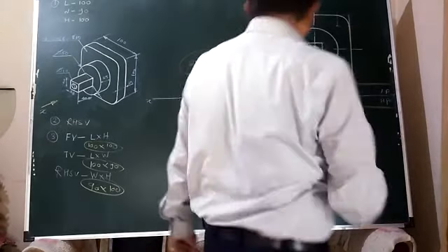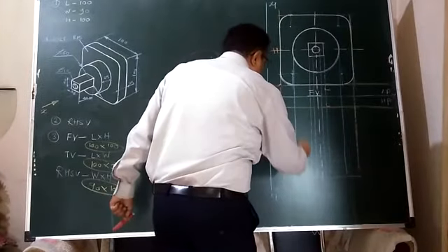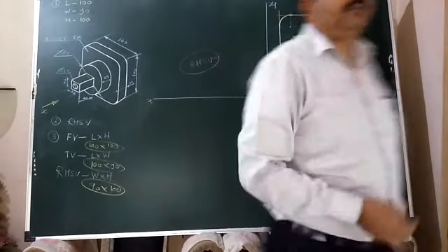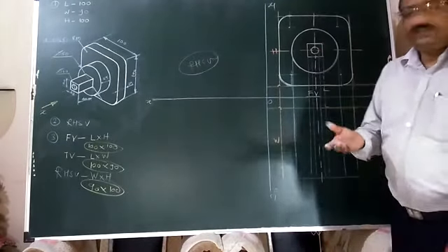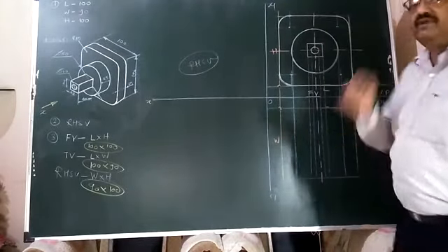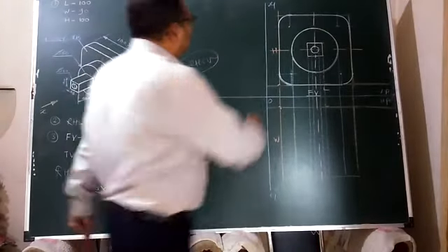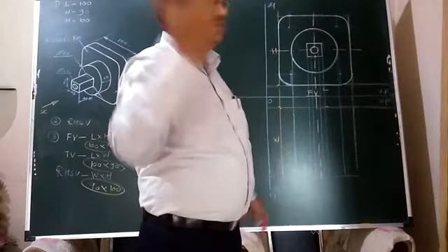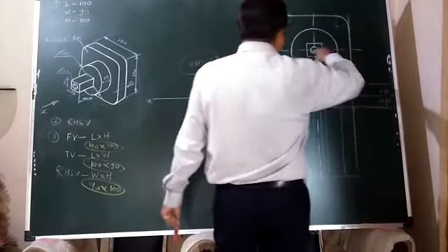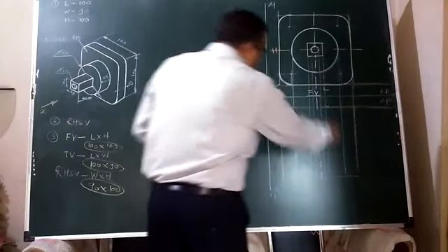Yes, each and everything has been well projected down by projection lines which are carrying 0.2 mm thickness. Means this blue chalk I have used because these lines should be very faint. Only the visible outline should be shown. The name itself of the line is visible outline. It should be visible. The rest of the things should be very faint. So accordingly, projection lines I have drawn here.